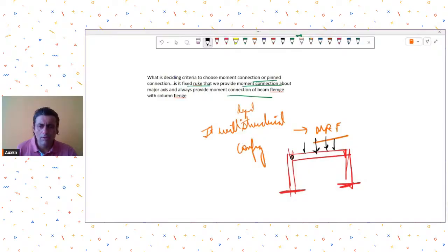Even with a shear connection, there will be no problem as to stability of the system. But if there is a chance that it will be subjected to lateral loads also, this system on its own is not a stable system if the beam-column joints are shear connections only.